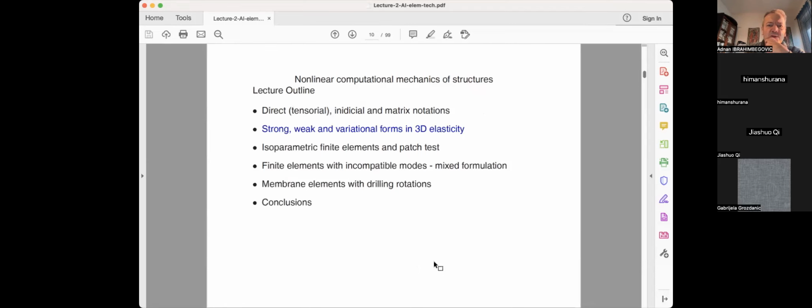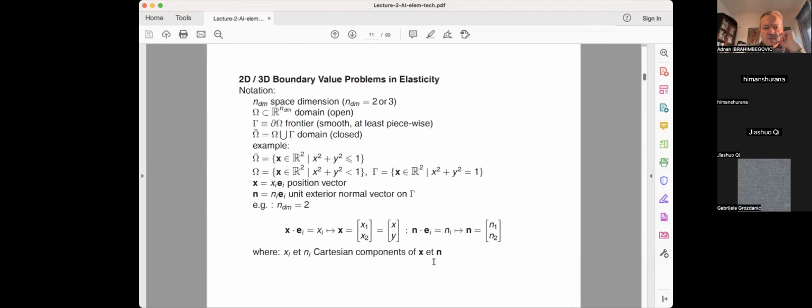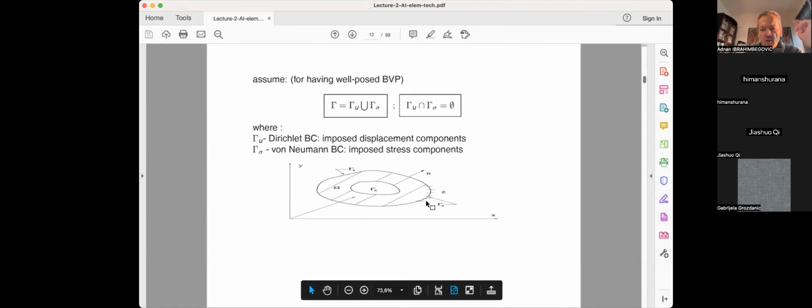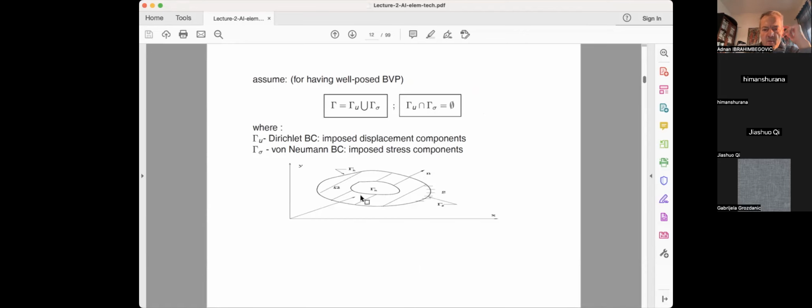So let me now go into the steps of defining a 3D elasticity problem, and in the process, recover what is the main difference from the 1D problem. First of all, the domain we are talking about is not possible anymore to represent as a single axis. You have to have at least a 2D or 3D case. It could be any complexity of the domain. Here it's pictured in the 2D case. I can have holes inside and so on and so forth. So whatever this part which is shaded is a domain, and everything else is the boundary around.